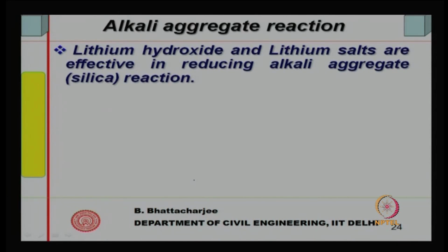in cement, right. They are there in the cement usually in small quantity, and this might form sodium hydroxide and potassium hydroxide. Now, these ones will react with some silica minerals, forming alkali silica gel, and this gel can absorb water and expand in volume, resulting in cracking of concrete. We will again deal with this somewhat later on when we talk of durability of concrete, but then there are some inhibitors which can stop this kind of reaction. Of course, you have other means of controlling them, but inhibitors can also be used.